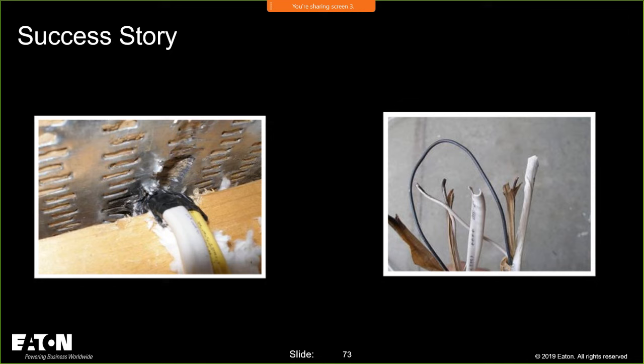But what you're seeing is, and I'll just tell you this story briefly here, the electrician unknowingly drilled through a gusset plate that came from the home run circuit that went from the panel board up to the first outlet inside of the bedroom. And when he pulled the conductor through, it stripped all that wire and caused a lot of issues with damaging the home run circuit.